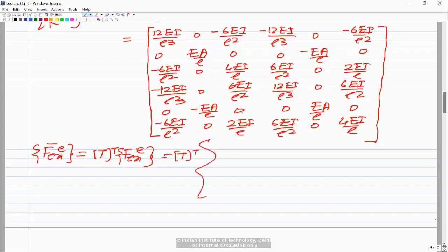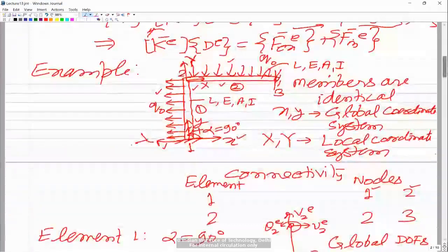There is no axial load. You will have to see here that this is the local y axis and the load is in the same direction. So as per this coordinate system, this q naught is positive. And there is no distributed load along the axial direction. So qx is equal to 0 and qy is equal to q naught.